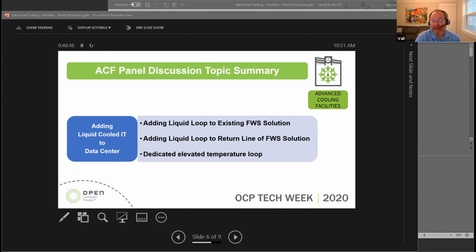It's done all the time. But then when you start doing direct evaporative cooling with a 100% economizer arrangement, you introduce the issue of high humidity and dew point control, and the control strategy becomes more complicated.